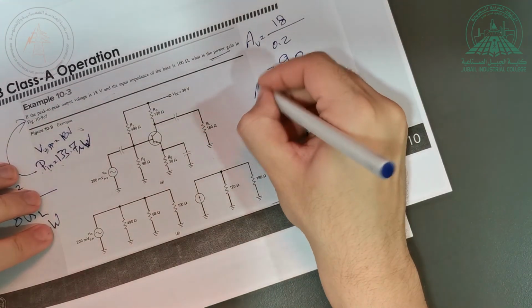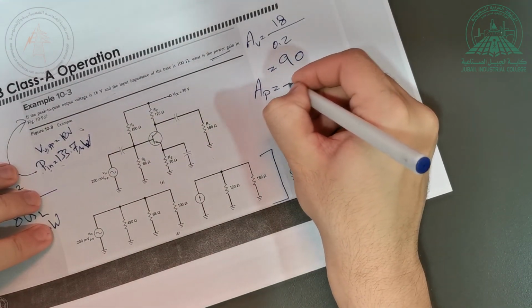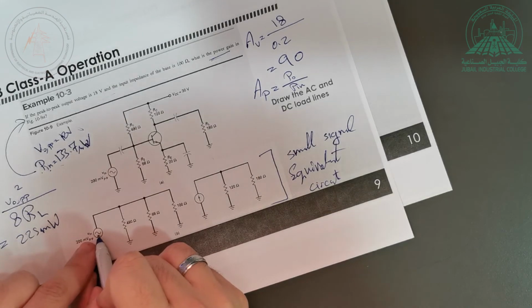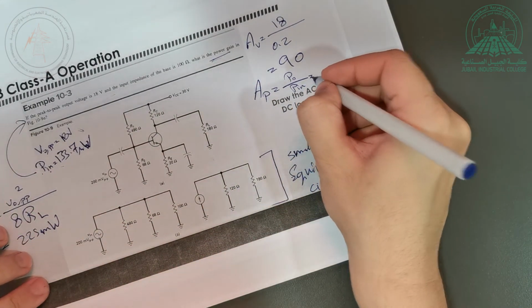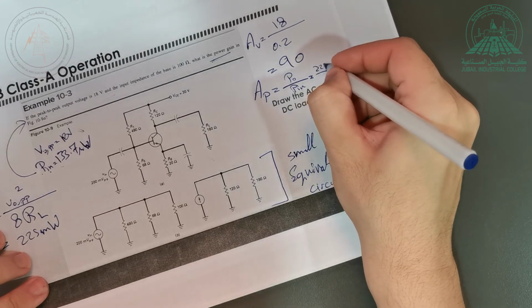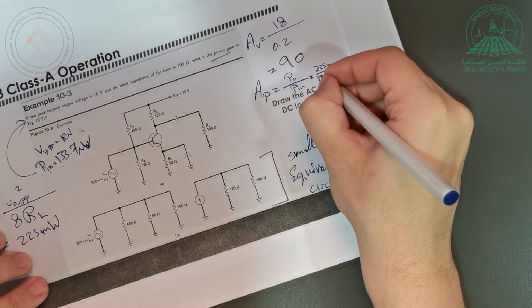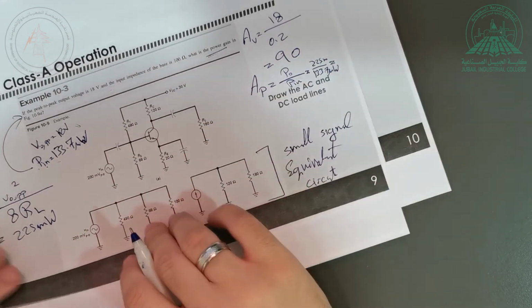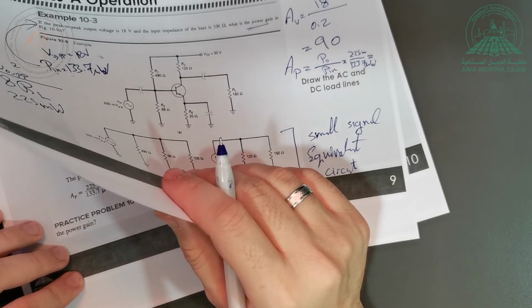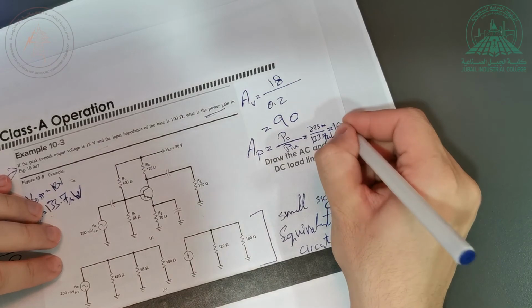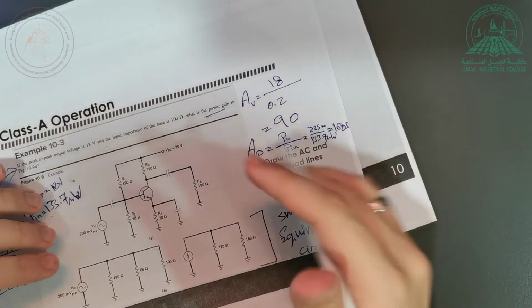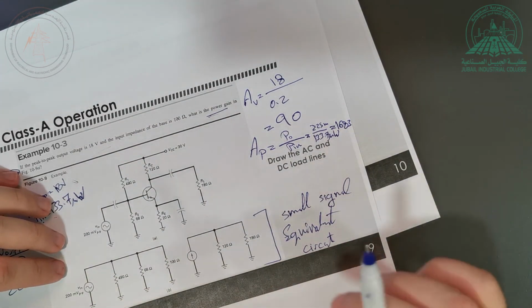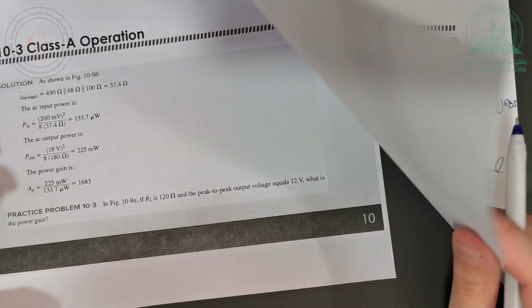So how about the AP? How about the power? How much was it amplified by? It's equal to P out divided by Pn. And this is not efficiency. I just want to see how much the power has been amplified, the AC power. So it is 225 milli divided by micro. How much is that? 1683. Note, guys, the gain has no unit, because it's times. How many times? It means the power has increased by almost 1700 times. Okay, a large amount of increase. This is done here.